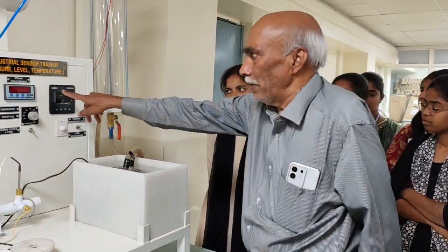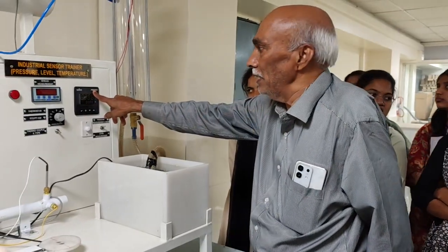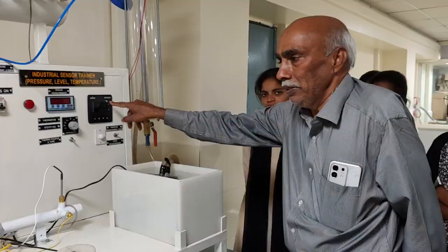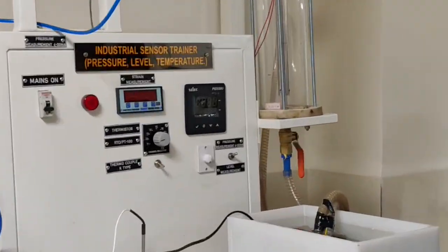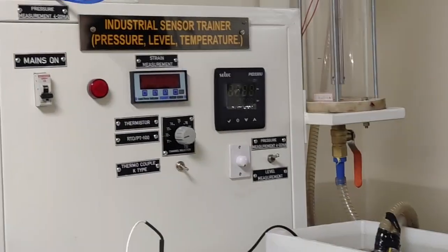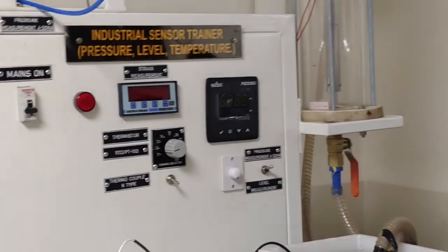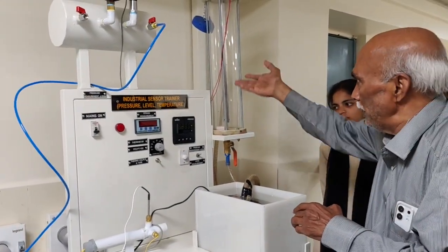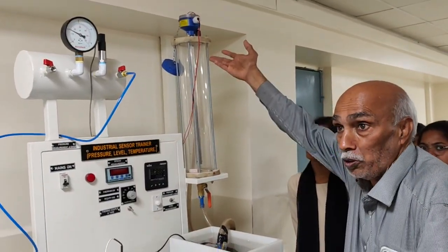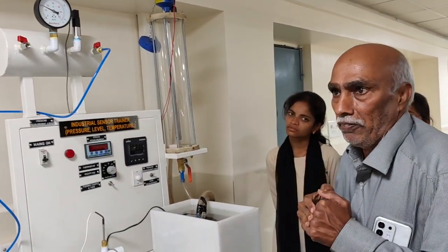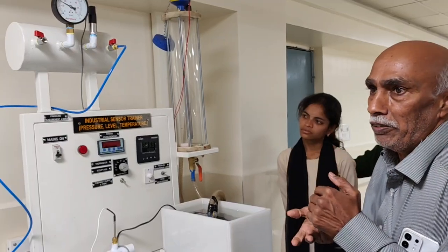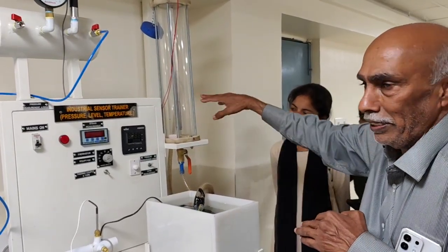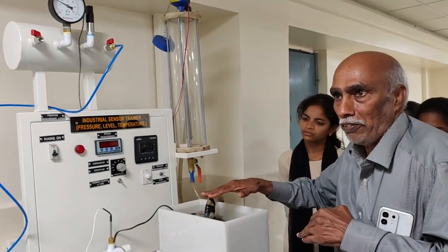PID: P means proportional, I means integral, D means derivative. When you are studying in engineering, these parameters will come. In control systems, you need to set the integral timing and derivative timing accordingly, for the gap up and down, overshooting and undershooting. Because sometimes if you are setting 200 or 190, it will go up to 200, 220. Suddenly 198 will never cut off. There will be overshooting and undershooting initially, because of the trial. So that you need to study. We are not giving you exactly 200 where it should cut off.